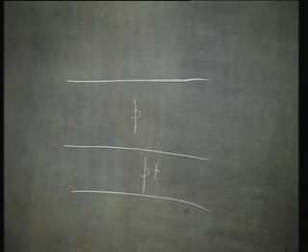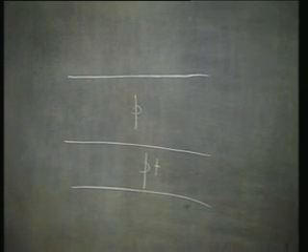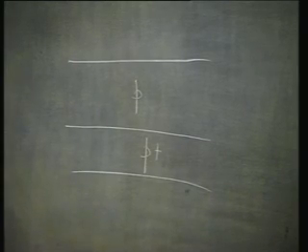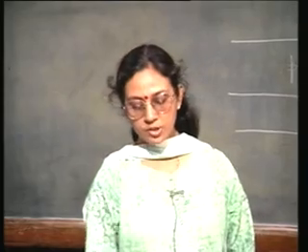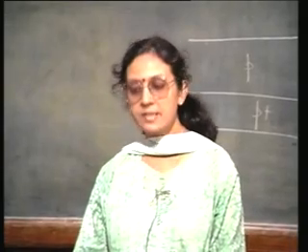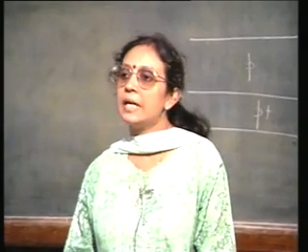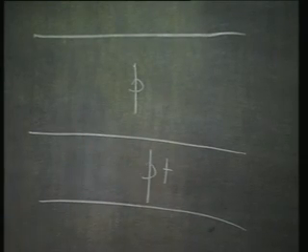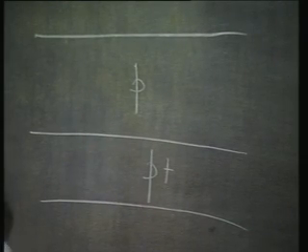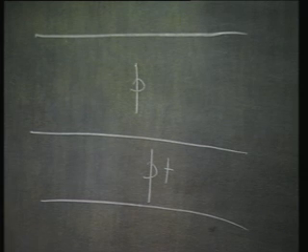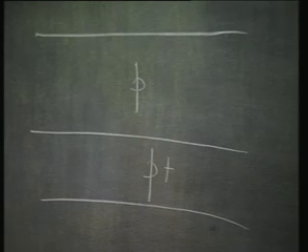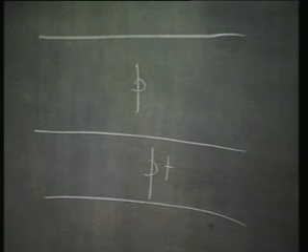Now, in order to realize a CMOS device in this, you must have an N-well. I already have the P type substrate. So, actually I am talking about an N-well technology which is compatible with the NMOS process flow. So, I need to have an N-well in this. Okay. Let me have an N-well.